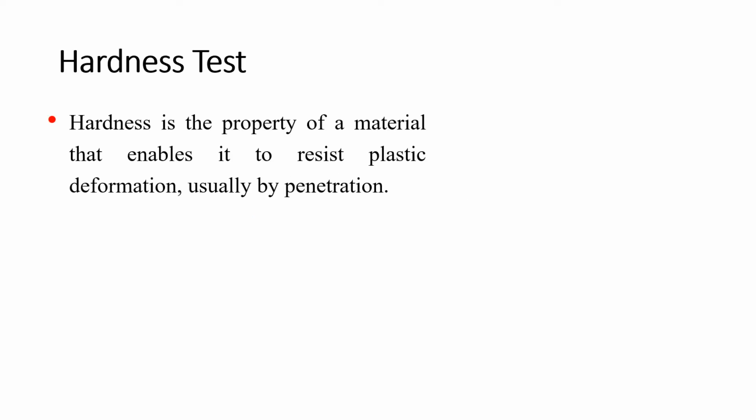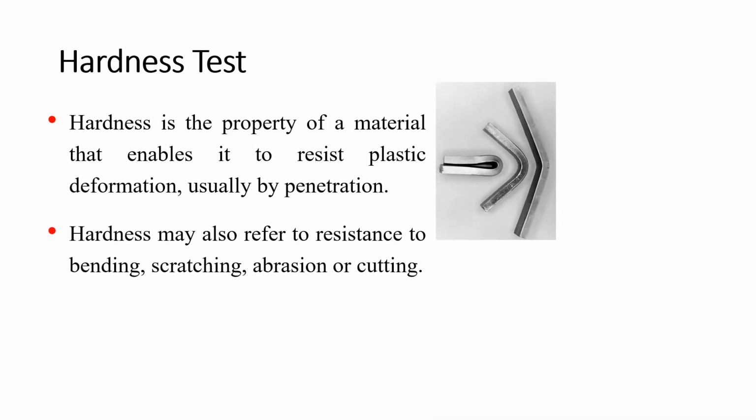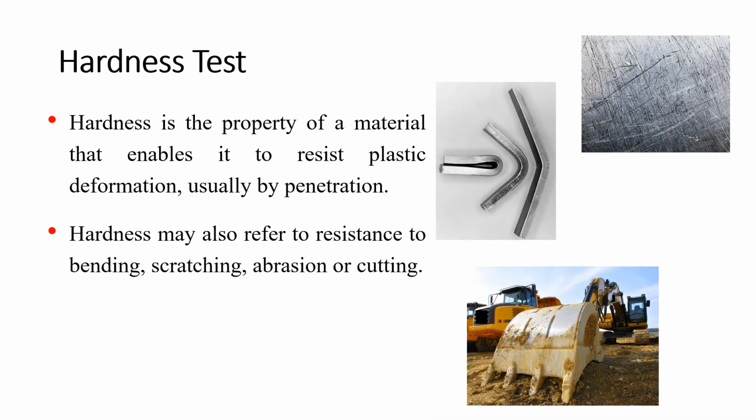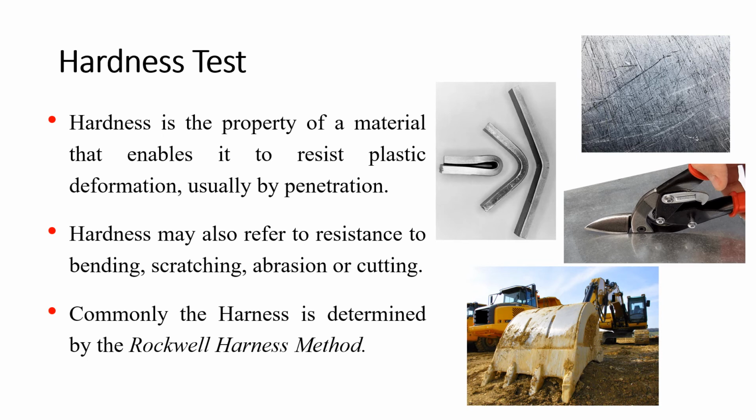Hardness test. Hardness can be defined as the property of a material that enables it to resist plastic deformation, usually by penetration. Hardness is related to resistance to bending, scratching, abrasion, or cutting. And the most common method to determine the hardness is the Rockwell hardness method.